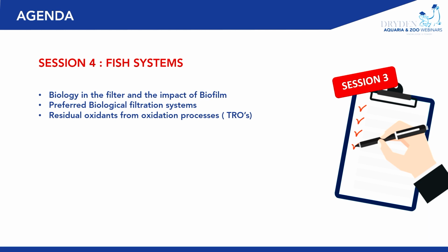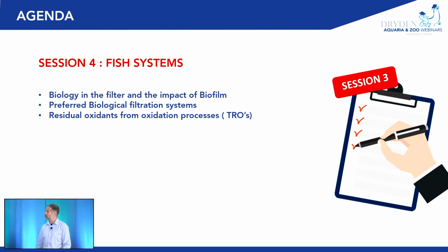Today, we're talking about fish systems: the biology in the filters of fish systems, the overall biology of biofilms, of nutrient removal, and oxidation applications or processes. Anything to add to that, Mike? Preferred biological filtration systems. Yes. We prefer that biological filters be purpose-built and designed to encourage and make nitrification as efficient as possible.